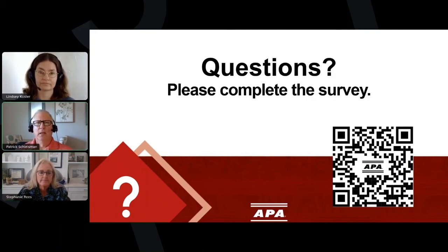That's a great question. CLT might not replace stick framing in single family or even in multifamily construction, although CLT is being used in panelized moderate income apartments at a reduced cost. Mass timber construction can be competitive in the traditional steel and reinforced concrete structures scenarios. As previously discussed, building heights can be achieved up to 18 stories or 270 feet, but many local jurisdictions haven't got there yet.